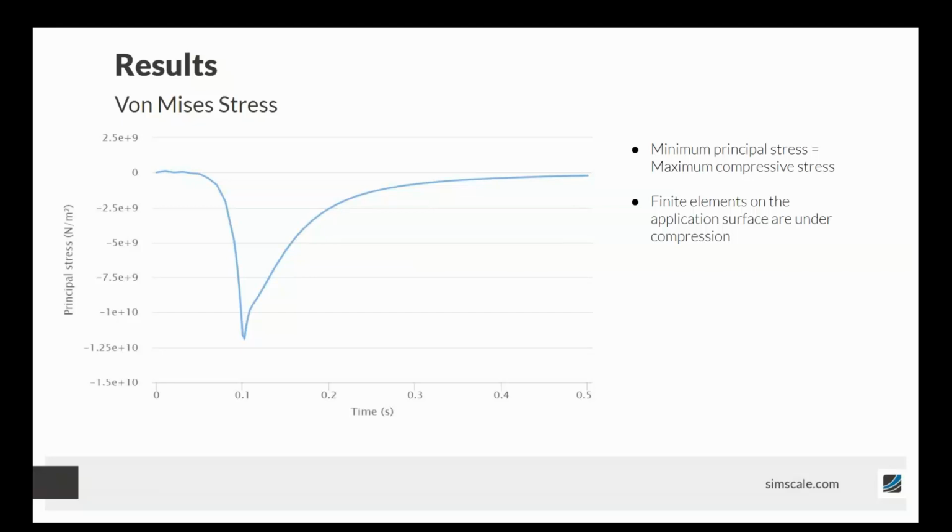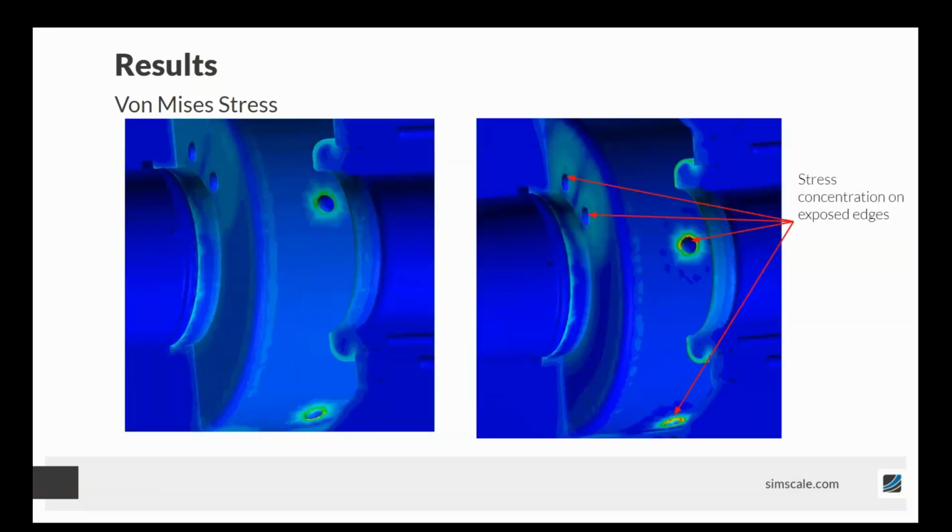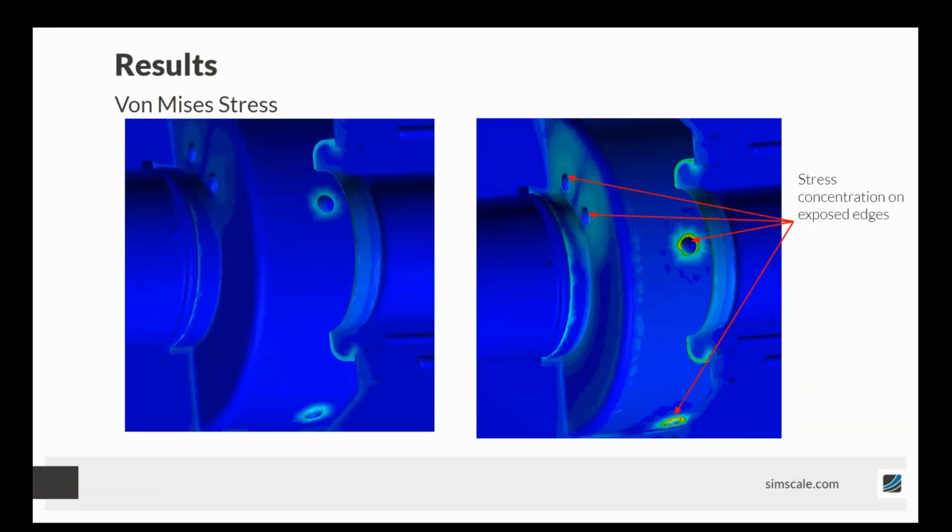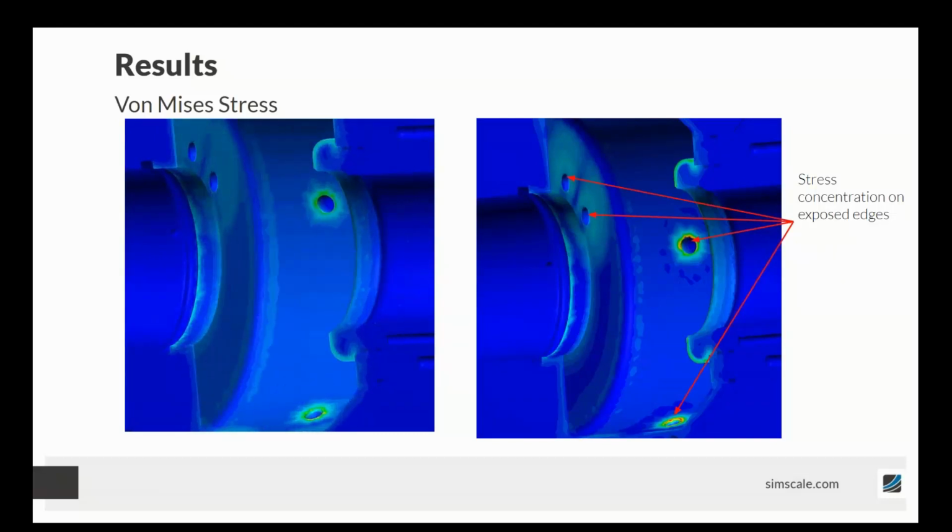because it may be that over time the surfaces, these steel surfaces, are really going to deform and get some very strange shape deformation, which may mean that the combustion chamber can't be used as effectively as when it was first designed. So this is the quantitative data that you can pull out of your simulations, and if you really want to see where the stress is actually concentrating, then we need to look, for example, here where we look at animations and at shading of the different stress components in the model.